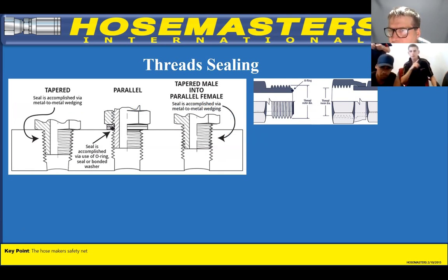There will be lots of JIC, but it's going by the wayside because it's metal to metal. See the little rubber seal here? That's a soft seal. And when it goes up against the face, it's a much better sealing proposition. Your John Deeres, your Masseys, all the American tractors that you have will be ORFS. That's why you have it.